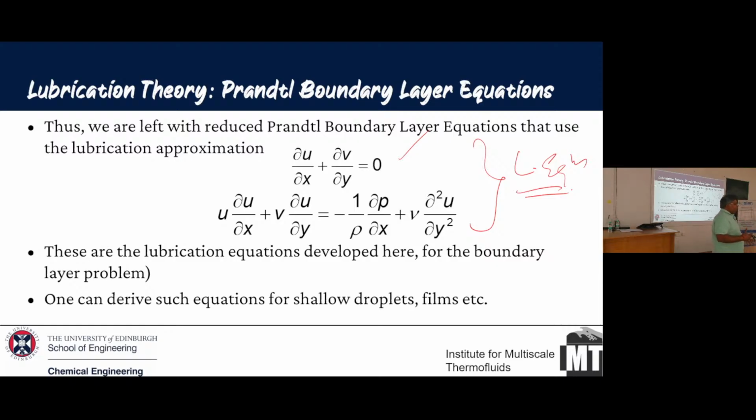If your substrate temperature is not as high, if it is not as warm, then you actually suppress the instabilities and you will just have very slow evaporation without any instabilities. So I think in case of methanol, we saw that if the substrate temperature was less than about 15 degrees, we must look at the paper, you won't see much of these instabilities. But then if you have these instabilities, it helps because you actually make the system more efficient.